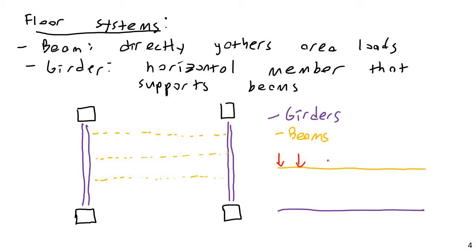There might be a uniform load all the way across it. This would be the uniform load from live load and dead load, usually maybe like 1.2 dead plus 1.6 live, that sort of thing. It'd be the distributed load from the area loads here. It could be simply supported, or it could be fixed, I suppose, but it would be supported at the ends.